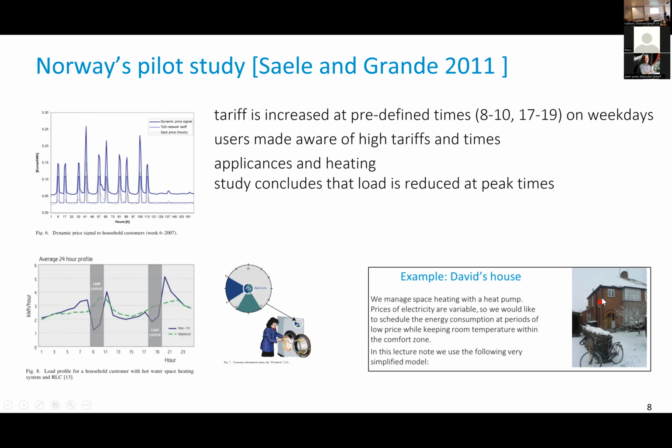Admittedly, it's not really done for individual houses. Not many people do that for their own houses, although David McKay did it for his house, but you typically do it for bigger buildings, like the EPFL or campus heating systems, or bigger systems, where the cost of having a computer that does the MPC is amortized easily over the entire system, and you have a SCADA to monitor your heating system anyhow.